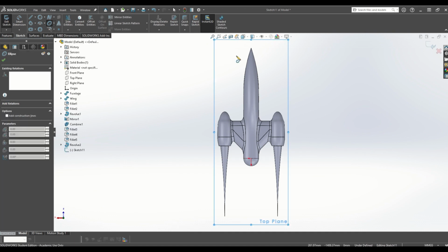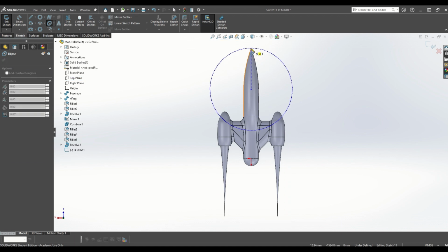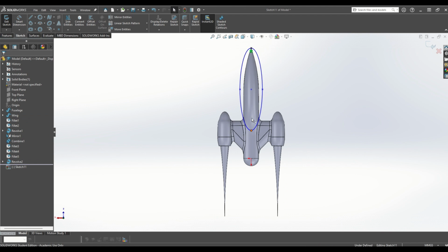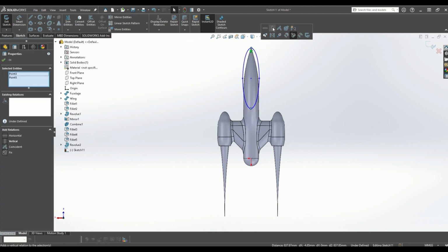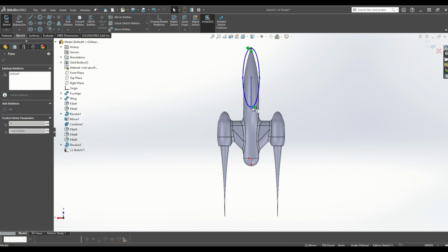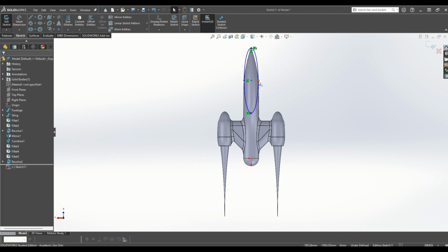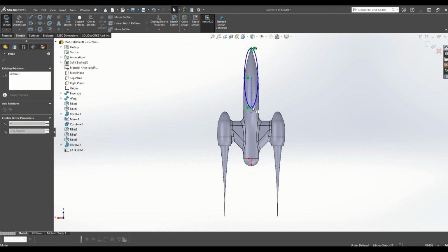Sketch. And I can create an ellipse that's around the center here like this. And here I might just bring it back here a touch. I'll make these points vertical to one another, the very end points of my major axis like this. I might bring in this just a little bit till it's on the actual side of my piece. There we go. All right, so I'll just relate them however I wish.